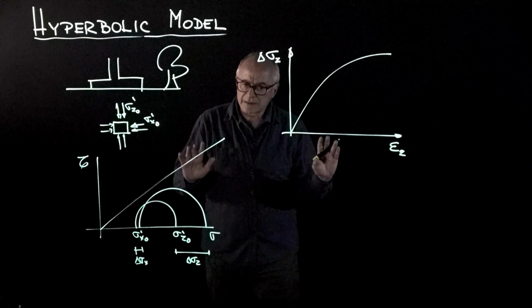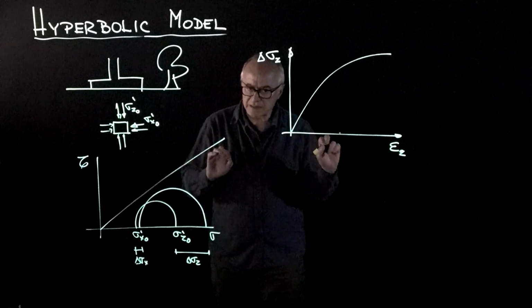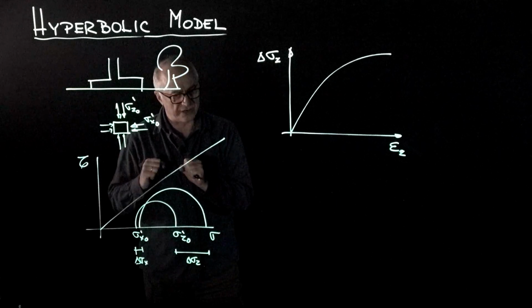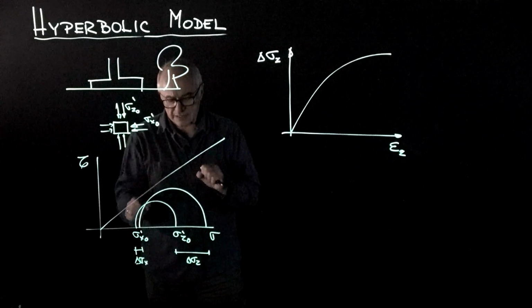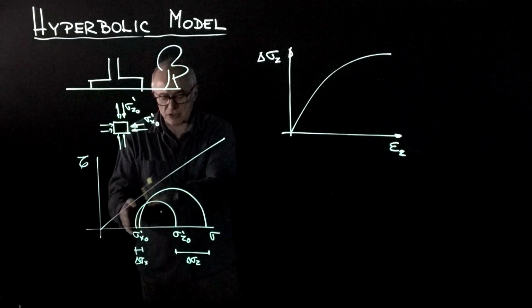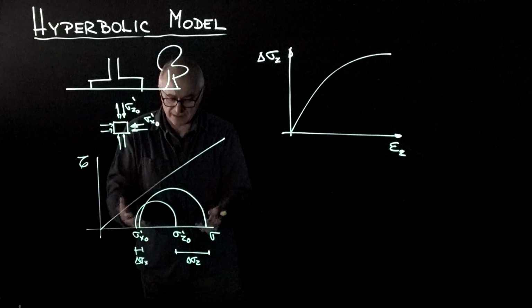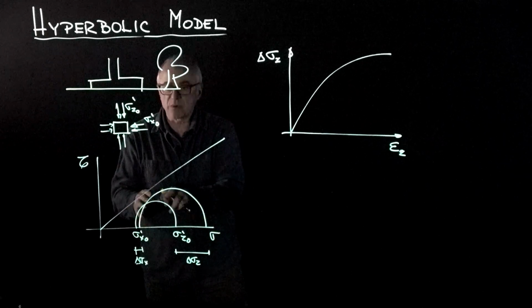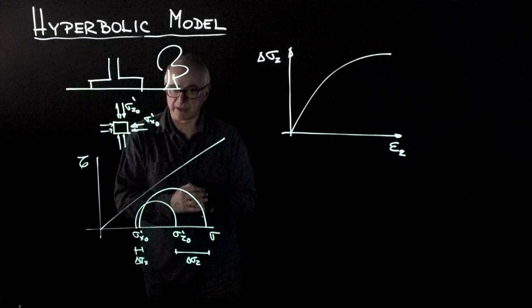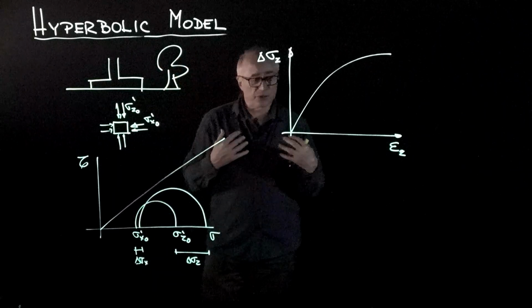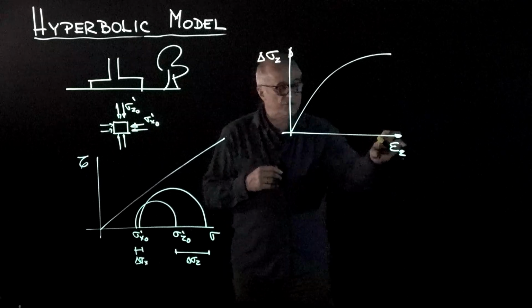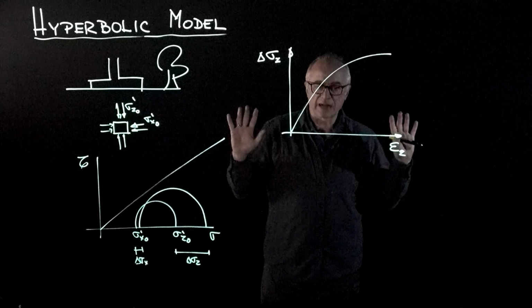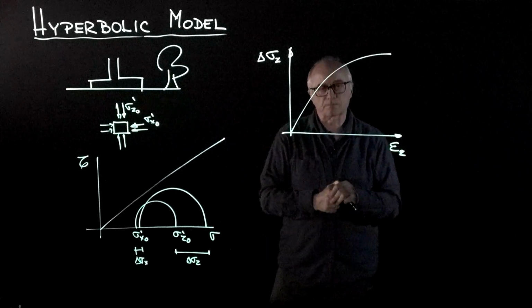To summarize this first point, I would like to insist we analyze failure with the combined stress state. In other words, we must take into consideration the initial stresses and the stress induced by the load, combine them to see whether the point is approaching failure. From a settlement point of view, we look at the strains caused by the stress changes because the initial stresses are already there before we start.